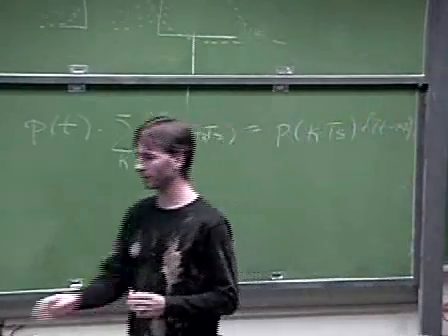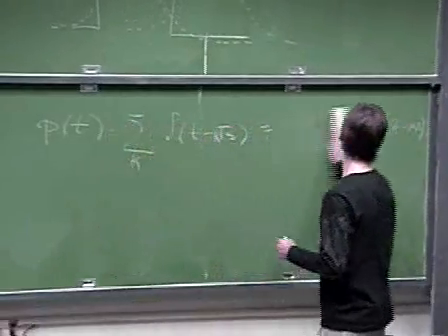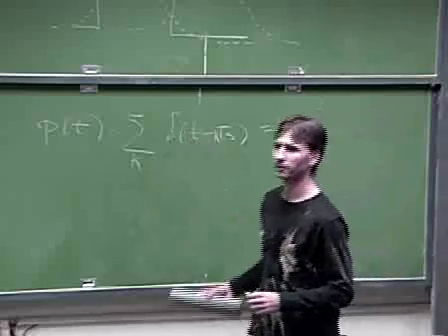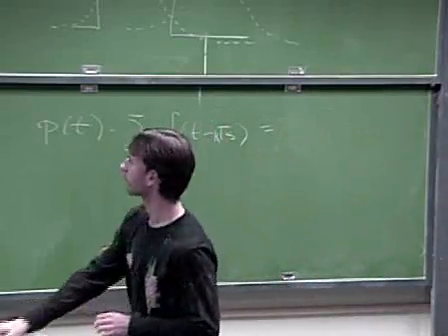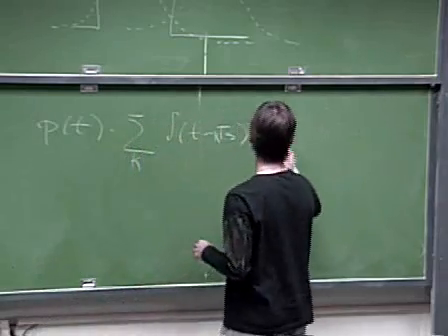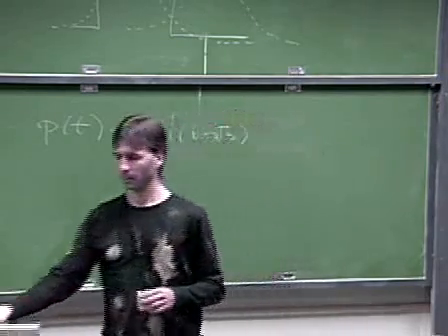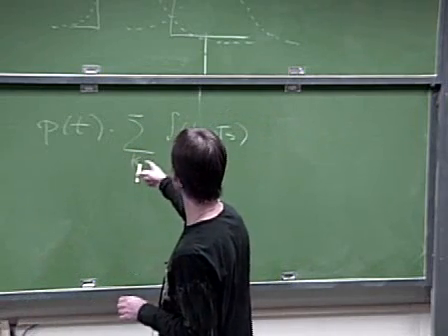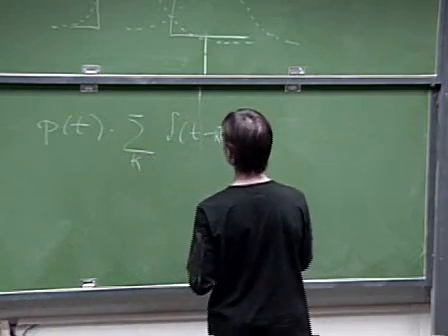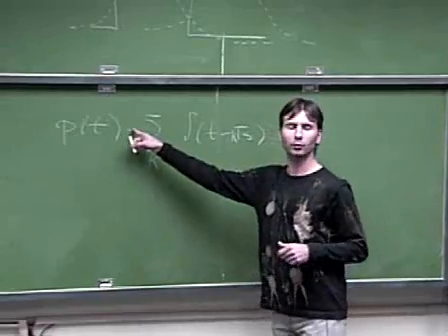Essentially these impulses are just picking up the value of the function at those points, and everywhere else you just get zeros. So you want these to be 0 everywhere except in one point. Now let's move these into the frequency domain. So what happens to multiplication when we go to the frequency domain?